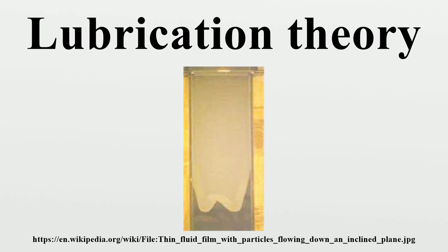Free-film lubrication theory is concerned with the case in which one of the surfaces containing the fluid is a free surface. In that case, the position of the free surface is itself unknown, and one goal of lubrication theory is then to determine this. Surface tension may then be significant, or even dominant. Issues of wetting and dewetting then arise. For very thin films, additional intermolecular forces, such as van der Waals forces or disjoining forces, may become significant.